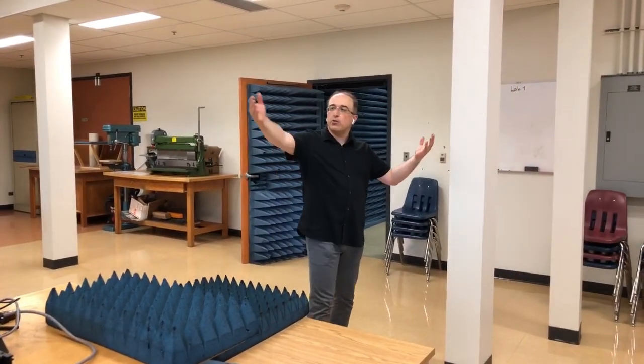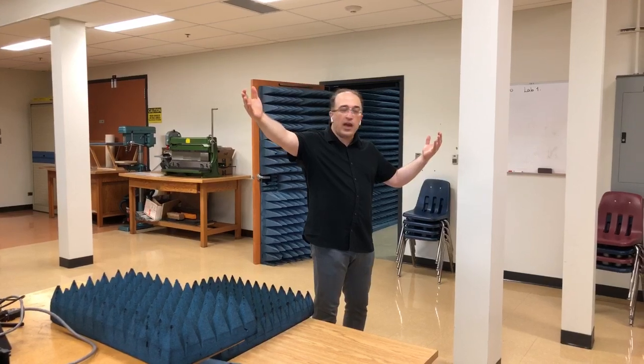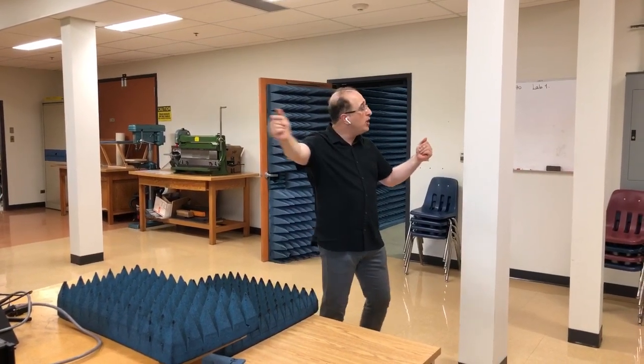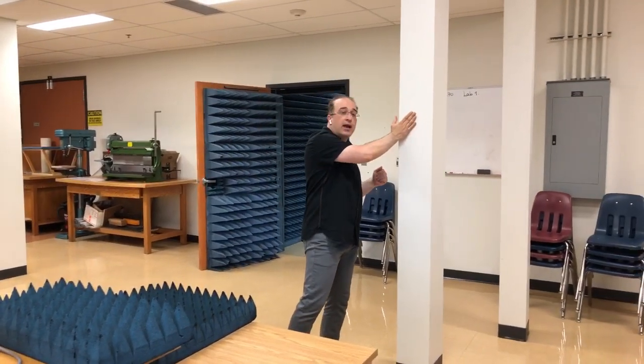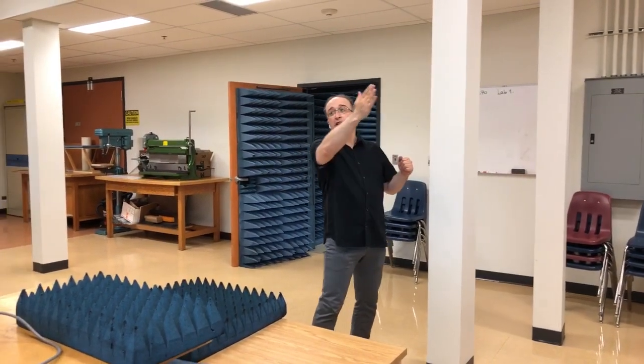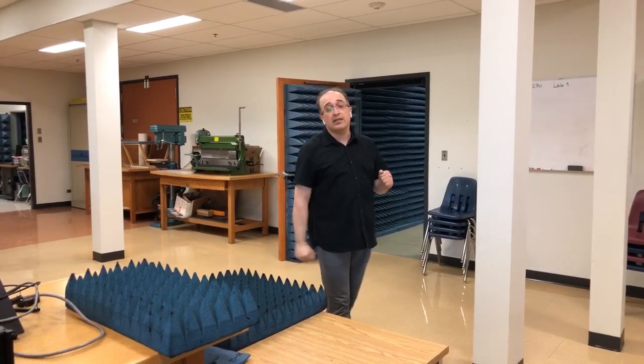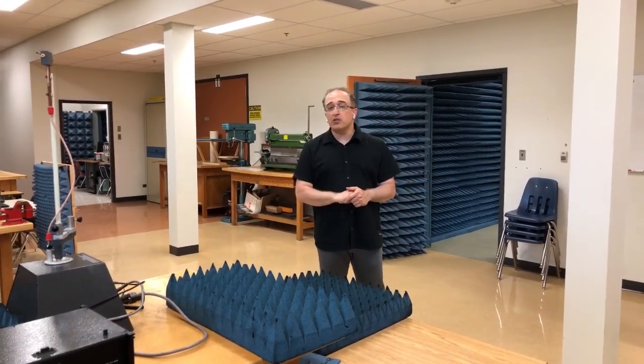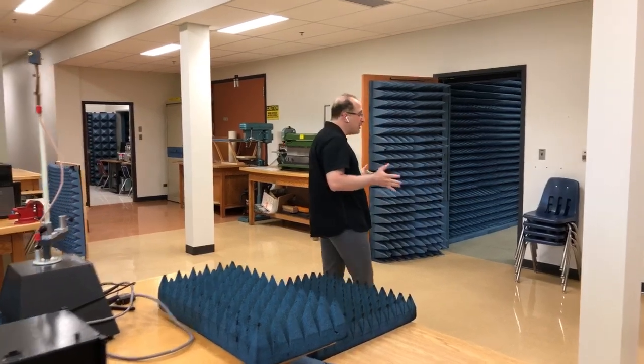If the electromagnetic waves are coming from the Yagi-Uda antenna, part of it could be received by the dipole, and part of it could go here, and a percentage of that would reflect back and again be received by the dipole antenna. This is not ideal for measurement. So ideally, you want to have this measurement system in an anechoic chamber.